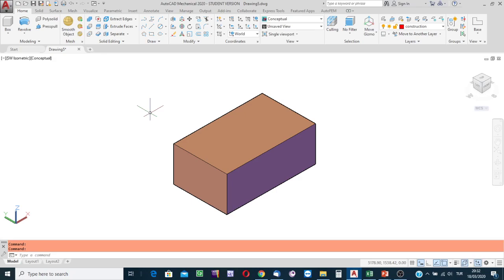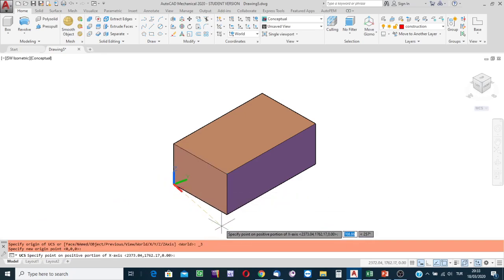One of them is going to be the axis of revolving, the other one is the profile. Okay. I like to use this facility to bring a coordinate frame to a certain specified location, the 3-point facility. Click and then, well, indicate this corner of the surface of the prism as the location for the origin. Click and then indicate this corner.